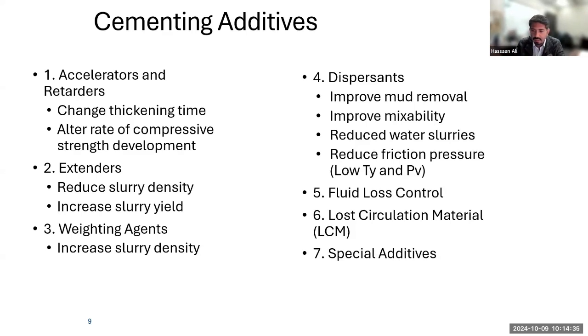And the cement can be used from a temperature ranging from below freezing in permafrost zones to almost 350 degrees Celsius, which is in thermal recovery and geothermal wells. The pressures encountered can range from almost 3,000 psi to 15,000 to 30,000 psi in very deep wells. In addition to severe temperatures and pressures, well cement must deal with weak and porous formations, corrosive fluid, H2S, CO2, and overpressured formation fluids. These cementing additives will modify the behavior of the cement, which will allow for successful slurry placement under the most extreme conditions.